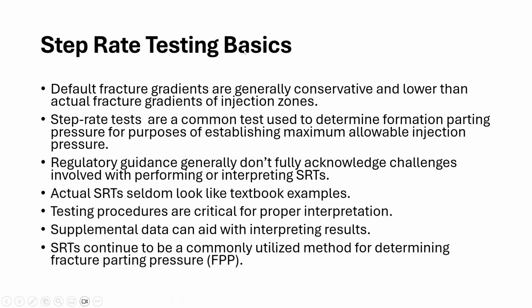Generally, we find that the default fracture gradients are conservative and lower than the actual fracture gradients you would find in injection zones. Step rate tests are a common test used to determine formation parting pressures for purposes of establishing the maximum allowable injection pressure and the rate that you get with that.